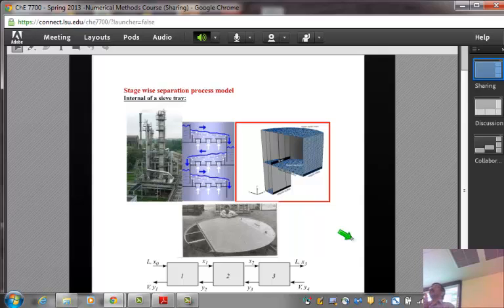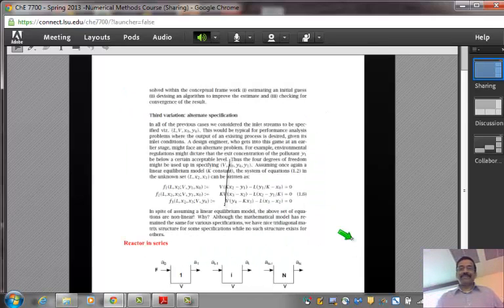So the same problem, the same model, but the specifications have changed because I've chosen to exercise my degree of freedom in a different form. Instead of specifying L, x0, V, y4, the four numbers known, I'm saying what I know is V, y4, y1 and x0, but I don't know L. When I have that situation, I will have the model looking like this.